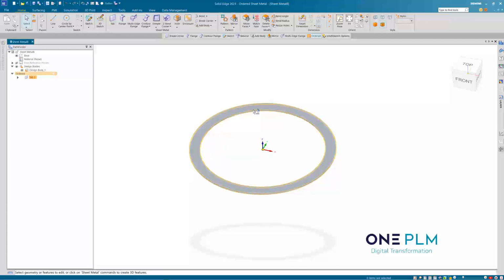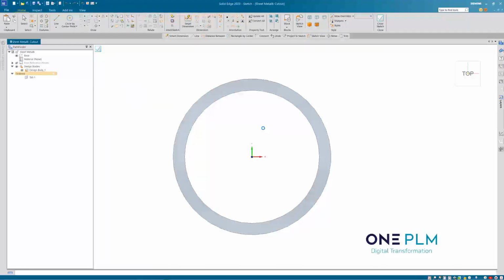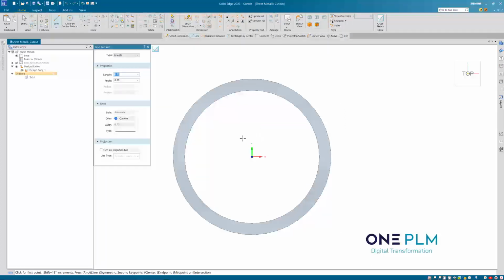Okay, so we could have made this tab more complex, but you'll understand why I'm doing what I'm doing on this next step. So this next step, I want to turn this into a 15-sided circle, if you know what I mean. So what I'm going to do is a cut. I'm going to select that top face, and then I'm going to go and choose my n-sided polygon.